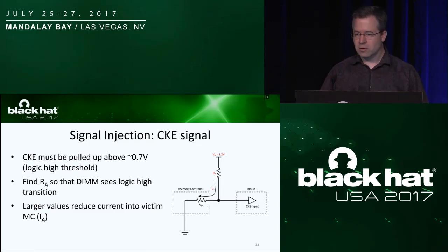And we did find out and confirm that all of the signal pins were in a tri-state mode except for the CKE signal, which is part of the self-refresh exit command that the memory controller would issue to the DIMM to wake it up.